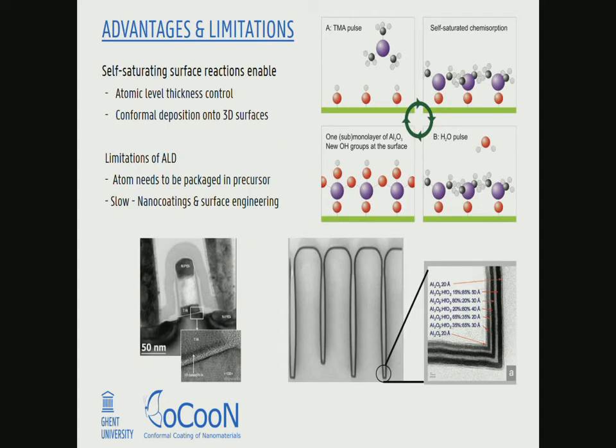And as mentioned before, the main advantages of ALD: you will want to use it if you're aiming for very accurate thickness control and if you're depositing onto very complex shaped surfaces. Unfortunately, it also has limitations.